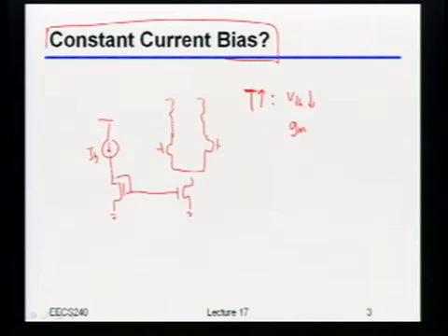It's going to increase. If temperature goes up, remember it's constant current. So what's V star actually related to? Even if I just had a long channel device, it's VGS minus VT, which, if I translate it, because remember my current is constant now.